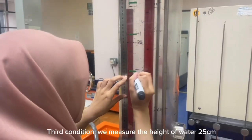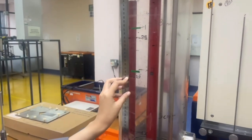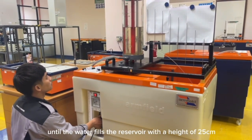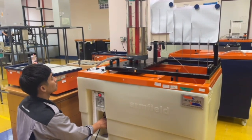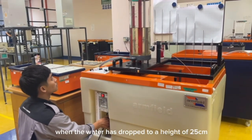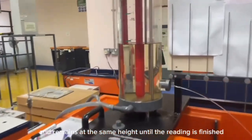Third condition, we measure the height of water 25 cm using the same orifice diameter of 4 mm. Next, lower the water speed and the adjustable overflow until the water fills the reservoir to a height of 25 cm. When the water has dropped to a height of 25 cm, make sure the water is in a controlled state without waves and remains at the same height until the reading is finished.